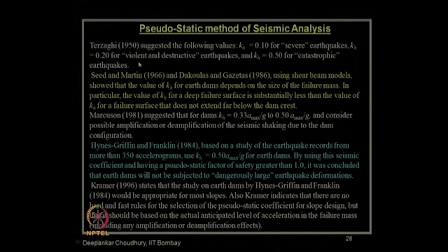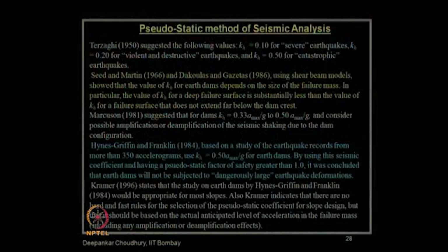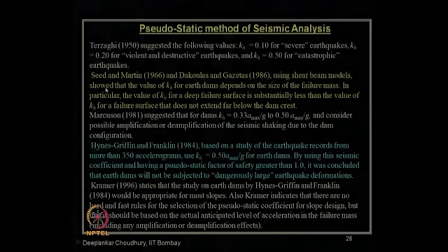So, in today's design method, if somebody is using these values, remember it will be primitive in nature. So, you can use it as a first step of your design, but you have to rely on the local seismic motion, local seismic hazard analysis, local site response analysis, and all these studies, so that you get a proper input value of your kh for this pseudostatic design.